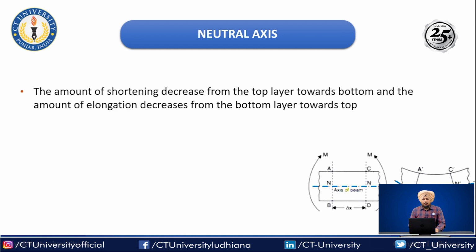And in between you can see from the top the length is getting reduced, and when we are moving towards the bottom, the length is getting increased, right? From decreasing to increasing as we move from top to bottom. And if you carefully see, in between there might be some layer that is neither getting elongated nor getting reduced. So here the concept of neutral axis comes into effect.